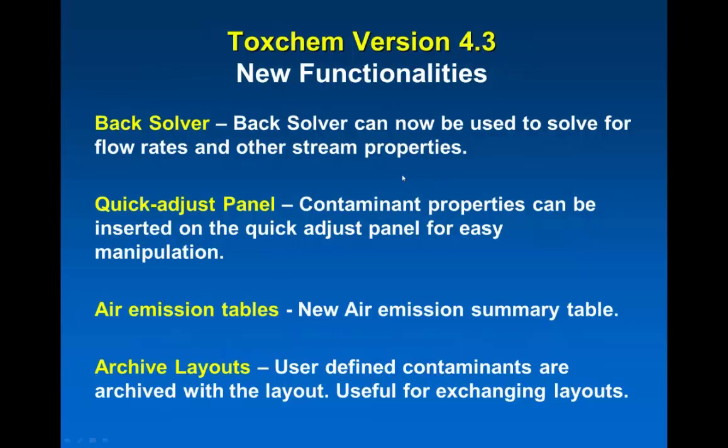With respect to the new functionalities, as I said, we have improved our back solver. Earlier in the back solver, we were estimating the concentrations in the influent if you know the concentration at some particular point in the wastewater treatment plant. We were solving for the influent concentrations, but now you can solve for flow rates. For example, if you know the flow rates at a certain point in the wastewater treatment plant, you can estimate what flows are coming into the plant from the influent. So you can do that now with version 4.3.